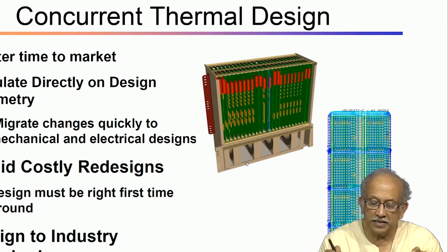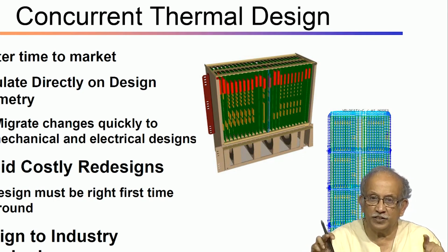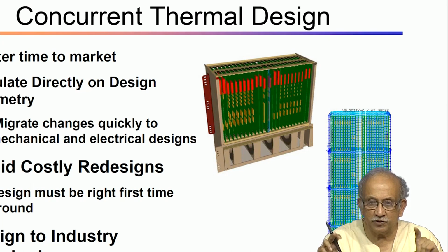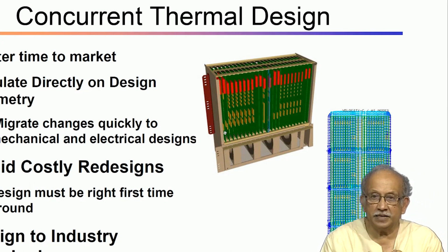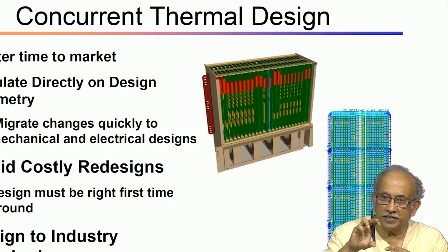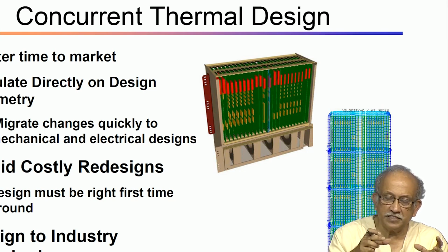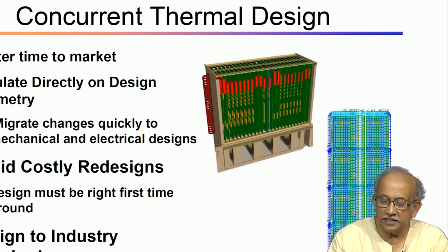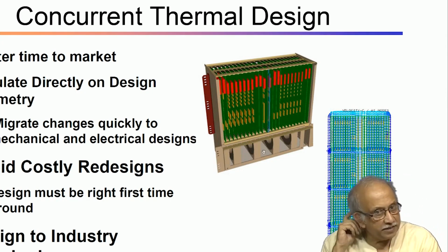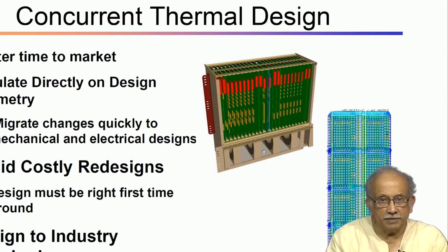This looks like a very odd 4U, normally we have 3U. Most of the equipment you come across is 1 or 2U, and 3U is fairly standard, because the plug-in PCBs have been standardized with the Euro card, which is typically 100 mm high. If you have a 100 mm high by 150, 160 mm depth card, you end up with a 3U. So, usually it is very easy for us to add an inlet from the other side. Same thing in reverse, no?